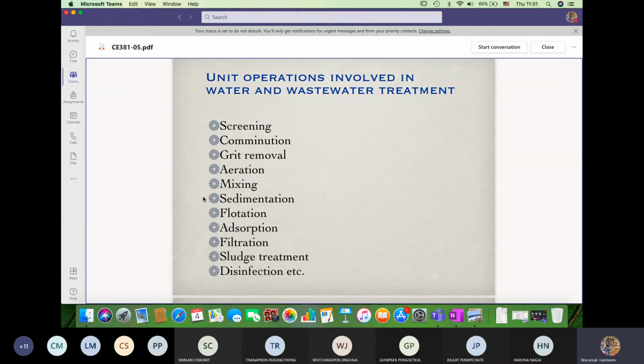We have to change the activated carbon within the specified times, and beyond the specified time, it may not give better efficiency. That is the limitation of the activated carbon, which carries out the adsorption process. Adsorption, just watch the spelling. It's AD, not AB. You may be familiar with AB. AB is absorption. Absorption is different from adsorption, AD.